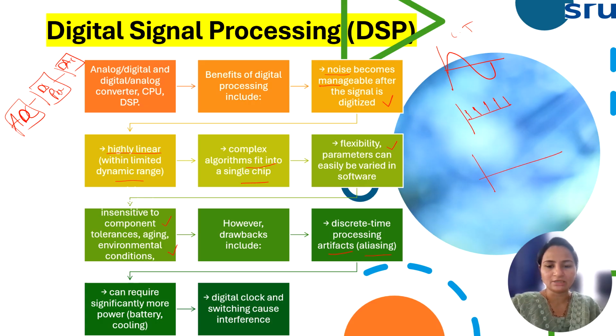After multiplying by the train of impulses, I have this digital signal: 0, then 1, again 0, then -1. As you can see, it looks like a sinusoidal signal, but the time is discrete in nature. If the amplitude is continuous and time is discrete, we call that type of signal a discrete time signal.